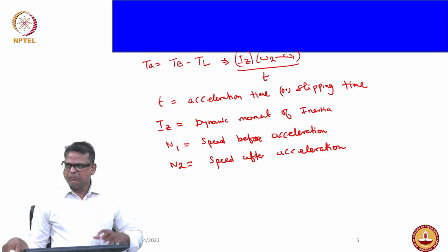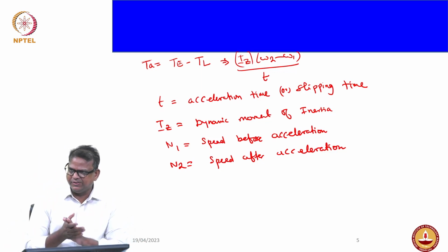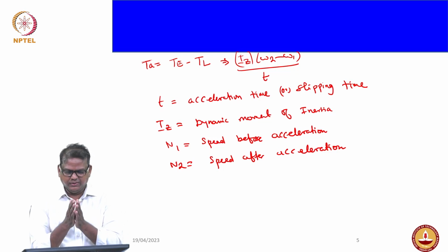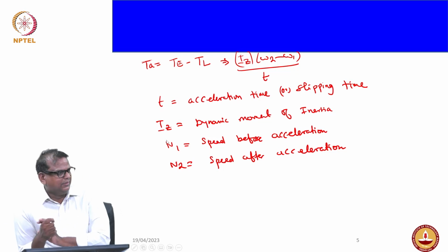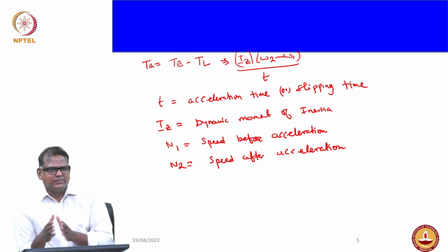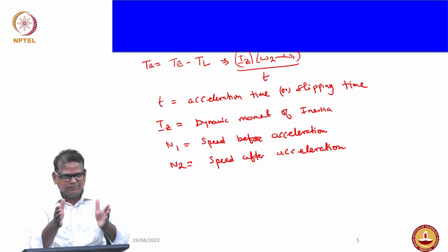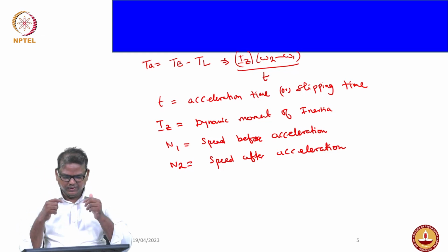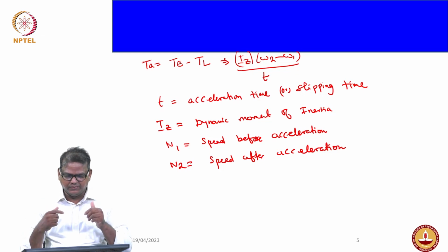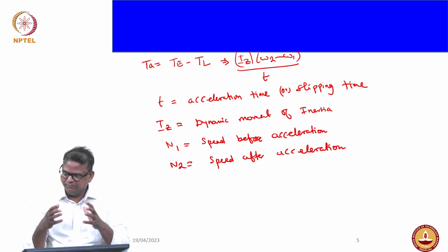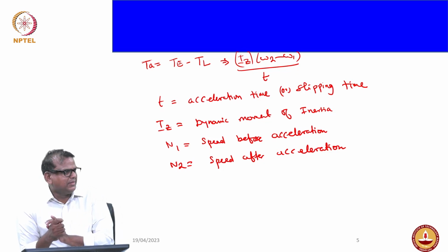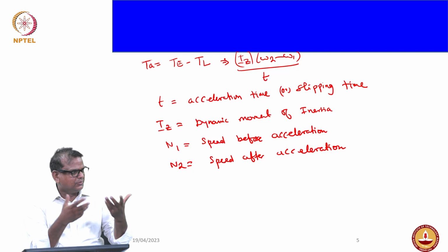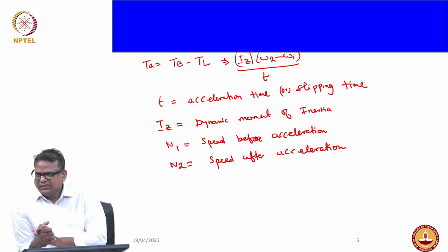Remember, moment of inertia, you know, right? Area moment of inertia. To find out the mass moment of inertia, you take mass into radius of gyration squared. That is what is given. But here, the vehicle is moving in a straight line, whereas your rotating components, when we talk about rotating components, we are talking about the clutch. That has to be taken care of, because when rotating, you will have an inertial effect also. That has to be considered.